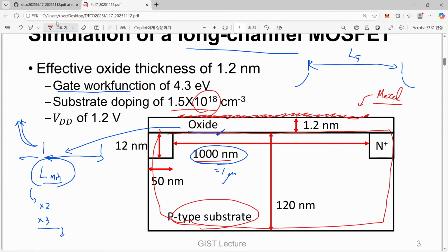devices. As I told you before, the reason why our previous devices have much higher doping density is that previously we had no ability to control the threshold voltage with work function engineering. The work function was more or less given, and there was only one single work function for one single type. If we have an n MOSFET, then we have a certain work function, and if we have a p-type MOSFET, then we have another work function suitable for that device.